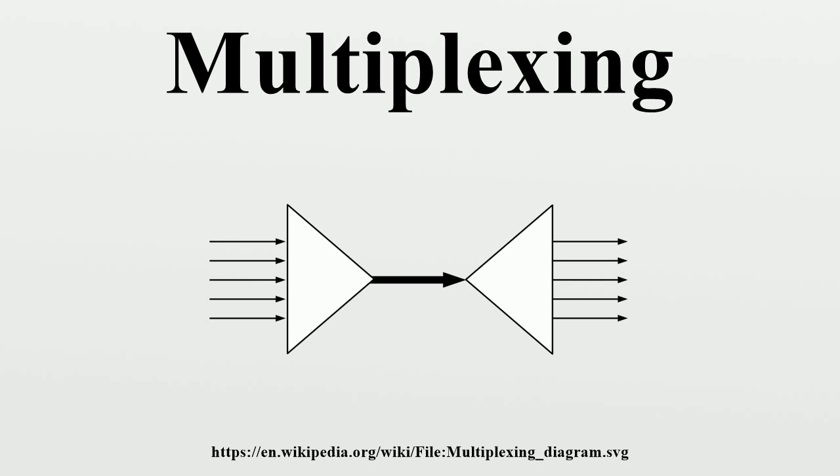Time division multiplexing. Time division multiplexing is a digital technology which uses time, instead of space or frequency, to separate the different data streams. TDM involves sequencing groups of a few bits or bytes from each individual input stream, one after the other, and in such a way that they can be associated with the appropriate receiver. If done sufficiently quickly, the receiving devices will not detect that some of the circuit time was used to serve another logical communication path. Consider an application requiring 4 terminals at an airport to reach a central computer.